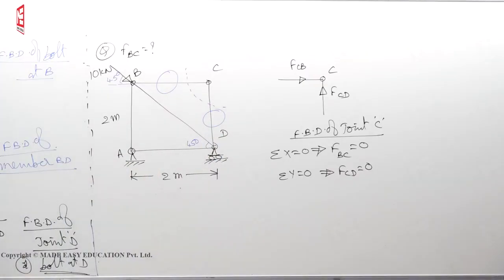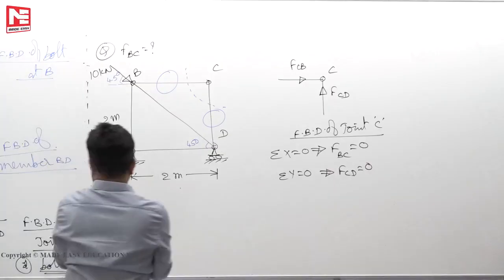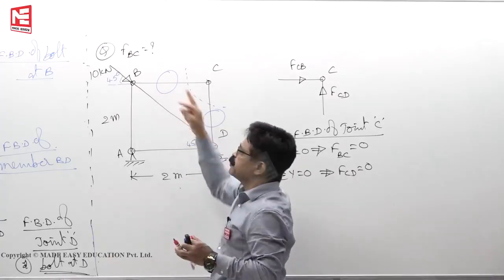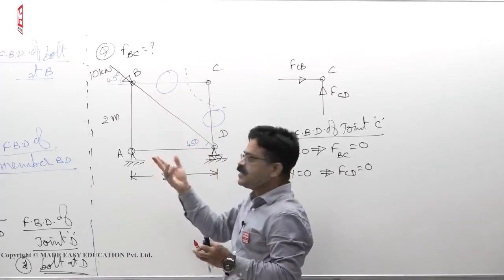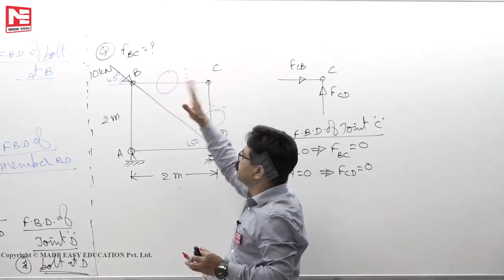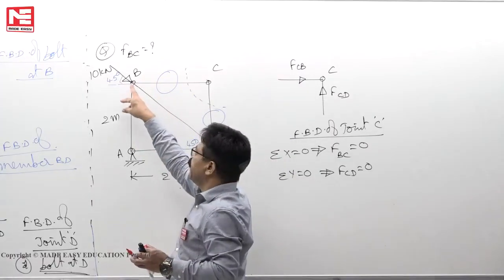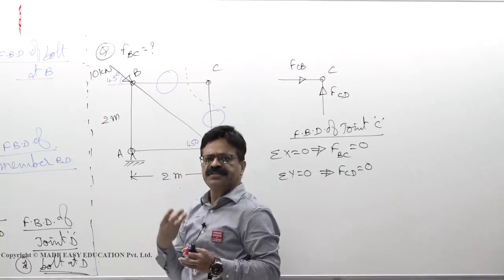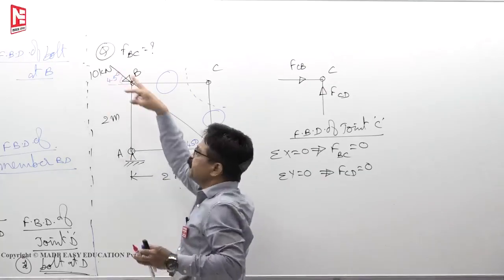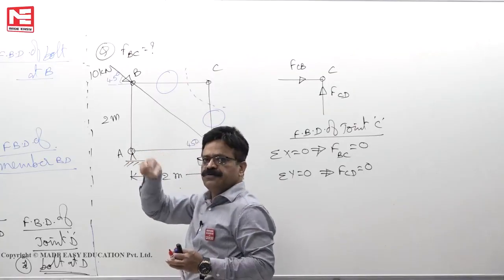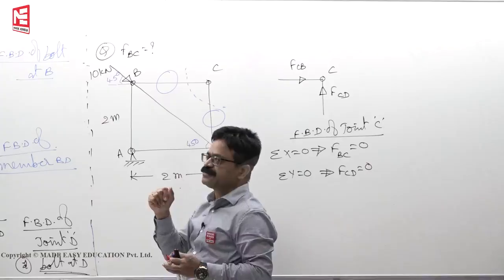Now, let us see this member. If at all any member force becomes 0, you visualize as if 0, right? Cut it, throw this piece out. Now this you have. At B now 3 forces are meeting, either 3 forces or 3 members, whatever it is. 10 kilonewton you can visualize as if that is a member whose force is say 10.